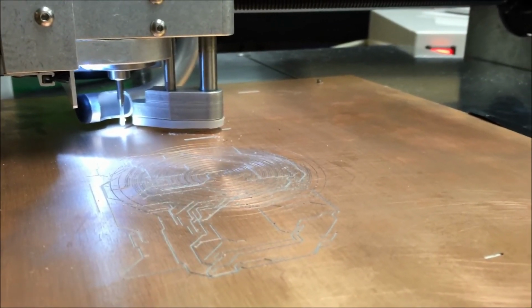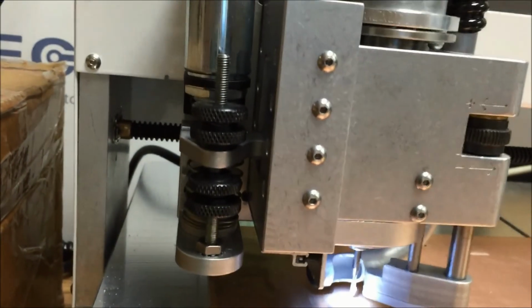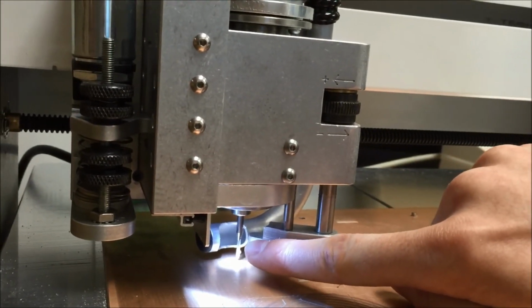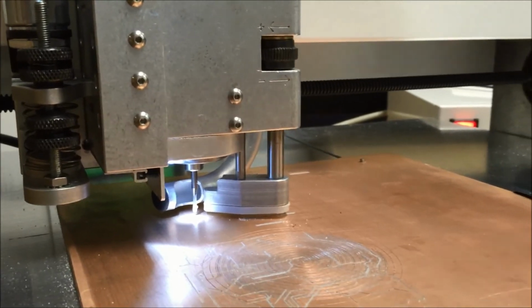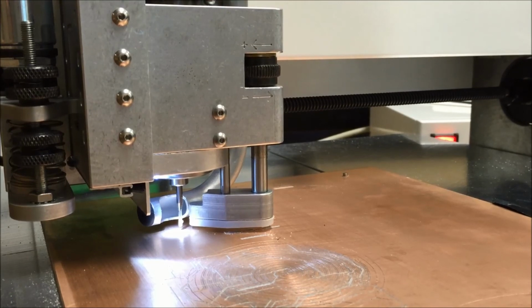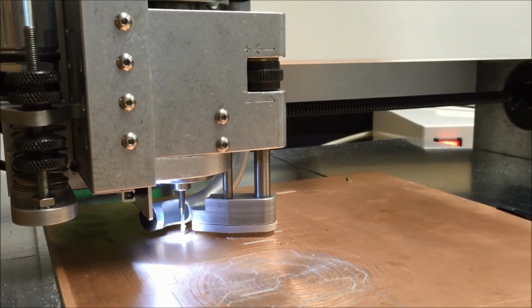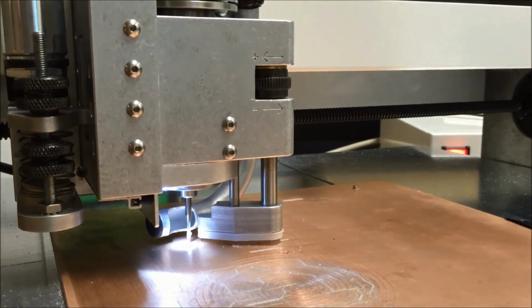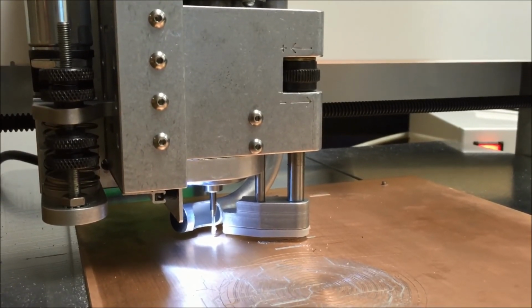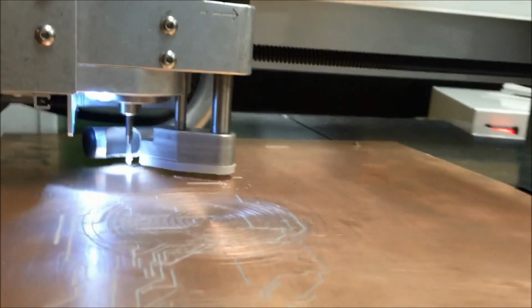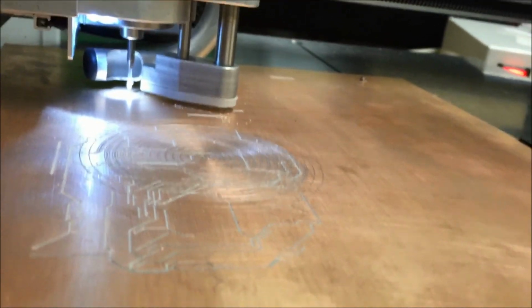But again, the cut depth is just set by these two adjustments on the machine. They're an upper and lower limit, and then also defined by where you actually put the bit in the head. Where I have it now is essentially where you want it. You want it minimally above the copper because the less acceleration the machine gets in the Z-axis, the less chance of causing unexpected damage to the board.